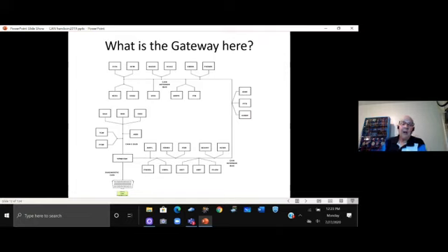If you want to, and they've got to know what the gateway is according to you, well then fine. Show them this diagram. This is a Chrysler, okay? Chrysler's using a tip-in module, and in that module, that's the gateway. How do we know it's the gateway? If you go up on the left-hand side, it's part of the CAN bus. If you go off on the right-hand side, it's part of the CAN interior bus. Now, there are other buses, but this is the one that's important, okay? And then it connects via the diagnostic CAN to the data link. Other than this, I don't worry too much about a gateway.